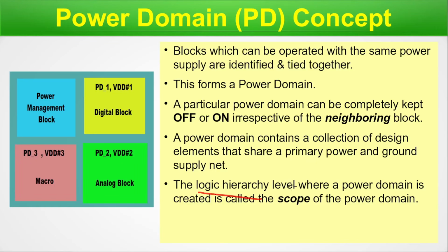The logic hierarchy level where a power domain is created is called the scope of the power domain. The scope of the power domains means this area. So this is the code-wise concept. Generally we code this in UPF. So there the scope thing in terms of the code you will find in the UPF series. There I have explained it with codes and examples and infographics. You can find that in the playlist.